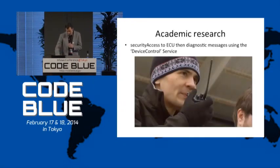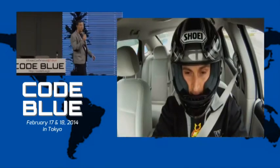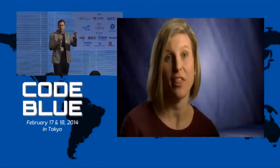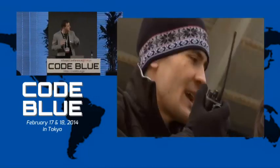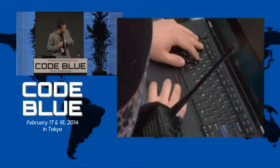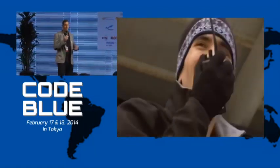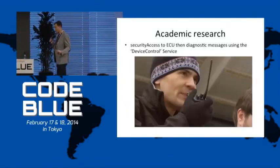This is actually how academic researchers did most of their attacks. And they actually did theirs remotely by compromising the telematics unit and had an IRC server actually on the car. Some kid could be messing with you just for fun. And we'll be applying your brakes shortly. Right about now. And you see they clamped the front brake. They used the diagnostic command after doing security access to the ECU, and they did it remotely.